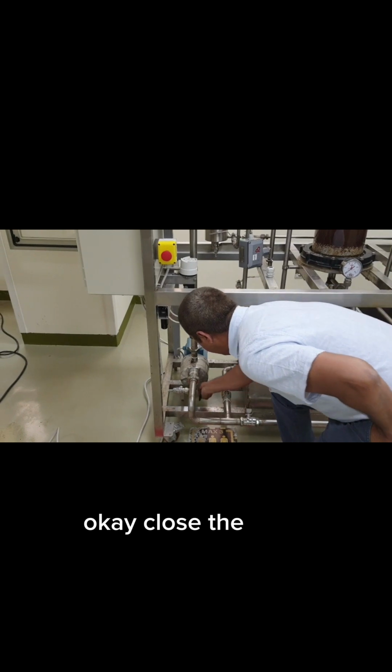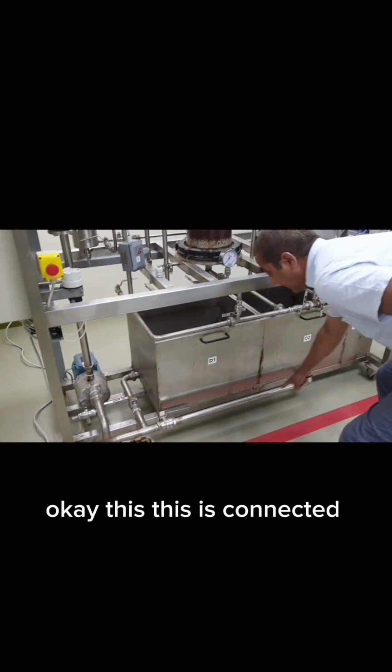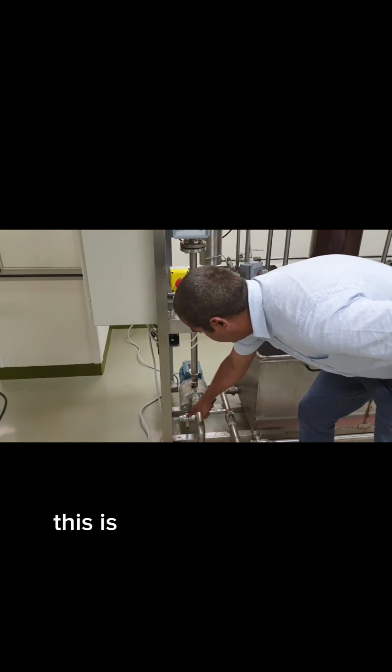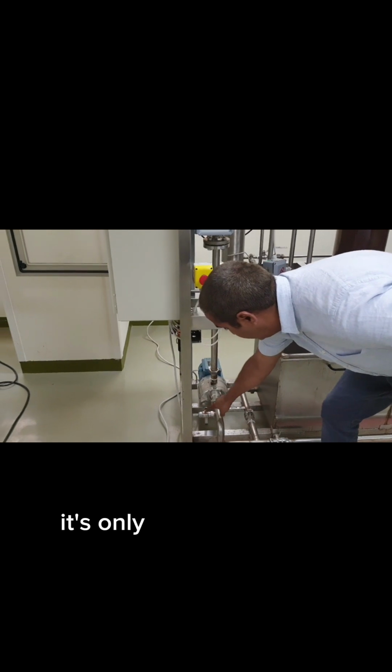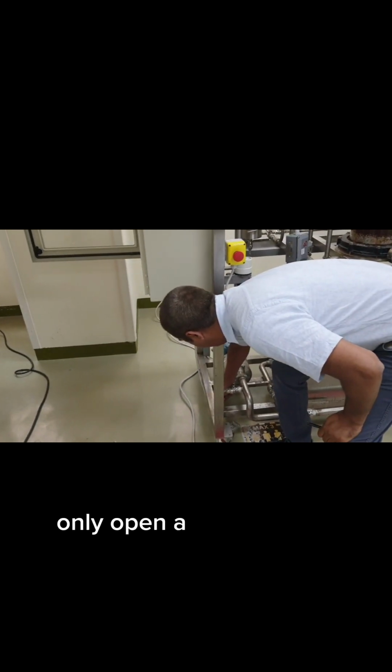We will close the valve because this is connected with the pump. If you look at this one, this should be closed because this is the sampling valve. You can take the sample from here. It's only for the sampling. And don't open it fully, only open it a little bit.